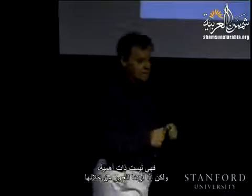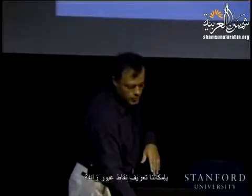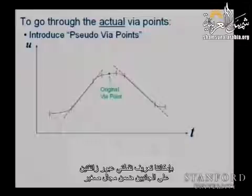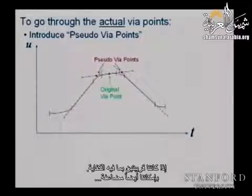In principle, the via points are just to make sure that we avoid certain spaces in the workspace. So it's not that important, but if we do want to go through them, then we have several mechanisms. We can introduce pseudo via points. Here is the original via point that we want to go to. We can introduce on both sides, at a small distance, two pseudo via points and do the planning for that. Then the straight line will go through the via point if we plan it the right way, if they're close enough.